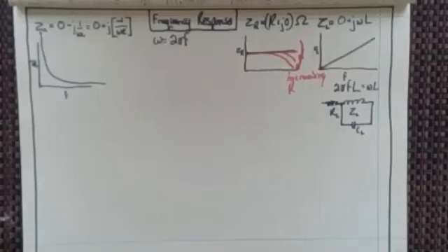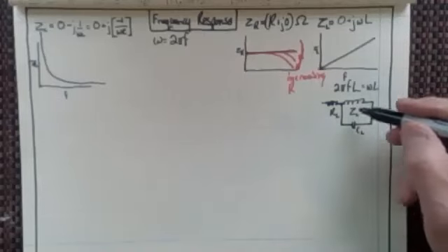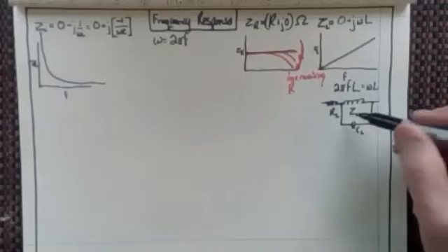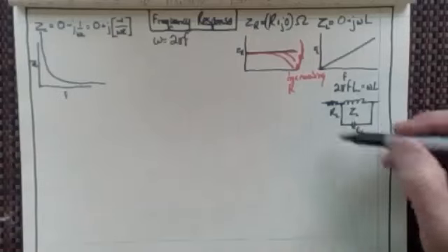These two leads that are coming out and joining it up to the rest of the circuit, we want to minimize. We want to make those leads as small as possible, because since those have two different voltages, those are going to cause a capacitive value, a parallel capacitive value with that inductor. So this is what we really have.